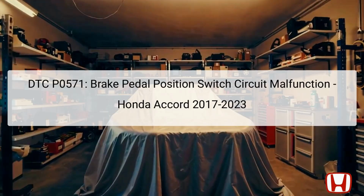The Diagnostic Trouble Code, DTC P0571, indicates a malfunction in the brake pedal position switch circuit of the Honda Accord models built between 2017 and 2023. This code is categorized under the Powertrain Control Module Fuel Injection PGM-FI systems. The brake pedal position switch is critical for confirming whether the brake pedal is engaged or released, which directly influences brake light operation and various safety features like cruise control.